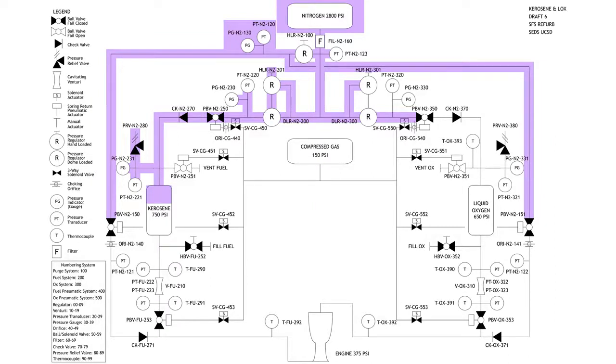Real quick, for the pressure regulation there, that's not by the ball valve, right? That's by the regulators. We do it 5 psi at a time. Yes, you're going to turn your hand load knob, just little turns at a time, to slowly pressurize your system. The ball valve just lets fluid flow through or not. That's an on-off system. That doesn't regulate anything.